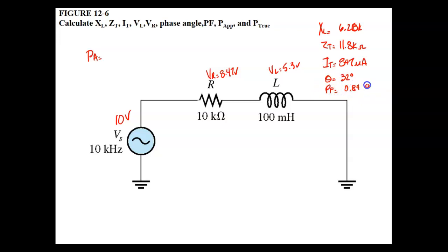And some people might call it 84%. A lot of people use percentage for the power factor. Well, I guess it's 85. I don't think so. It's true power over apparent power, but if you look at your triangle, then it's the adjacent and the hypotenuse. They're the cosine. The apparent power is the hypotenuse, and real power is the adjacent.